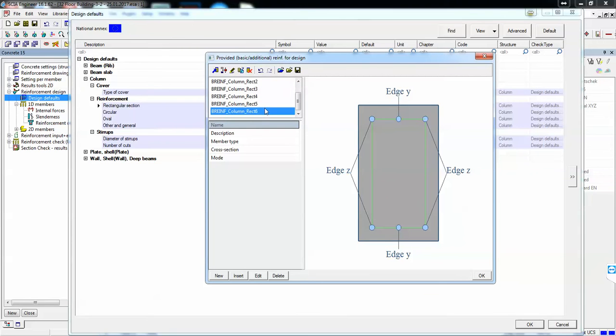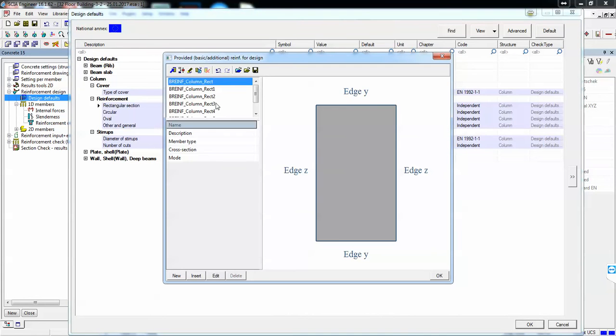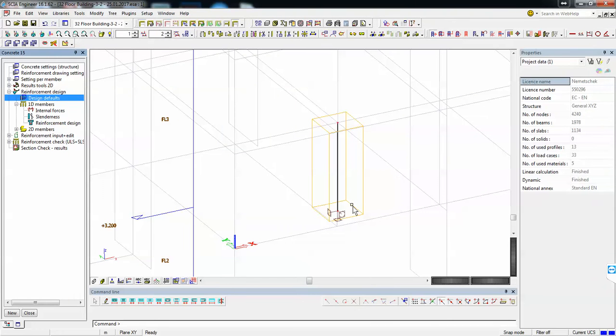And then it will complete with stirrups. So I can either let the program put reinforcement bars, or I can put them myself and have a good dimensioning. Okay, I can choose anything for now. You'll need a lot of bars as you have a very big column.